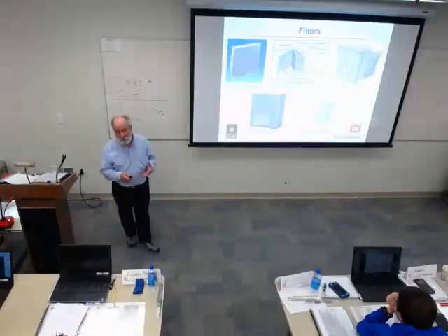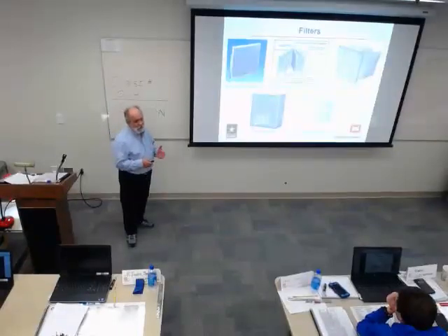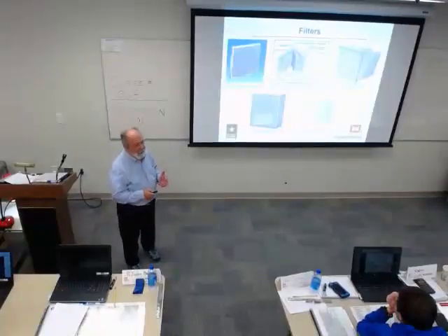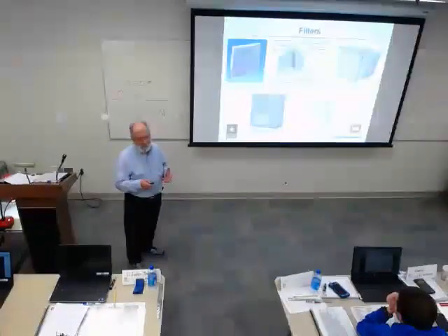We don't always have the option. On rooftop units, we're stuck with a 2-inch filter. And sometimes that won't get us through TAB, depends on where you are.